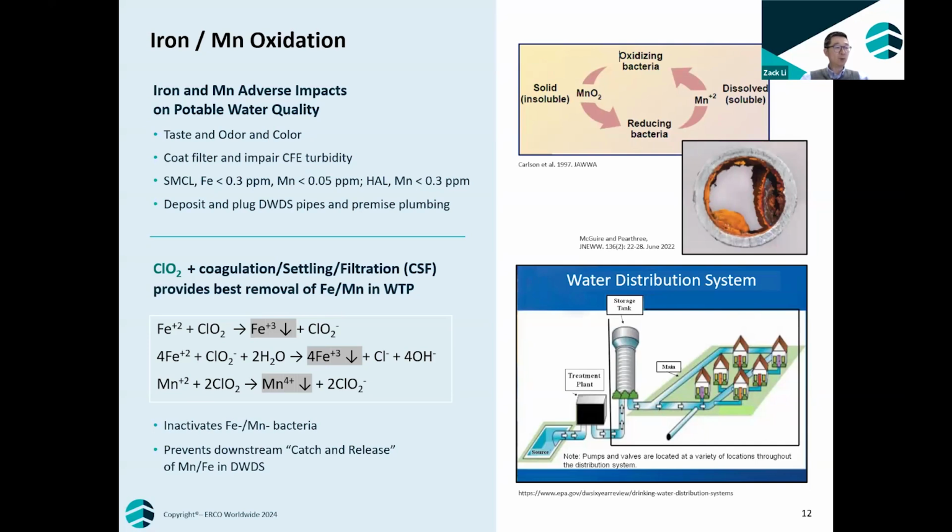Potassium permanganate, for example, is used to oxidize iron and manganese. Ozone is also used. Overshoot from permanganate and ozonation may redissolve manganese as permanganate ion in water. This can cause a pink water issue in tap water. Aeration and chlorination, on the other hand, is a very slow reaction and usually takes hours to days to complete the oxidation. Incomplete oxidation of manganese and iron can form colloidal forms of iron and manganese, which become very difficult to remove from the system.